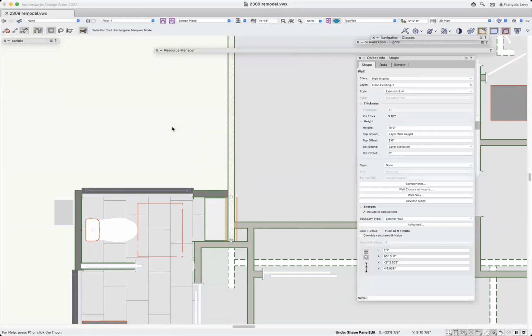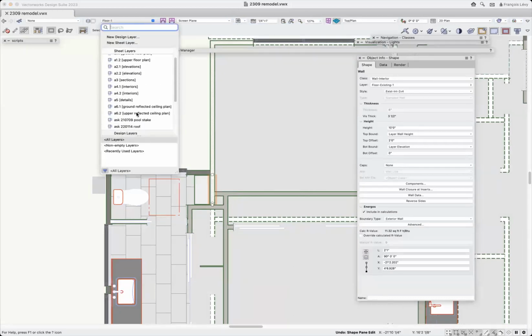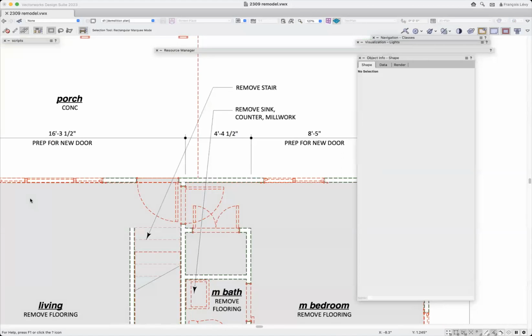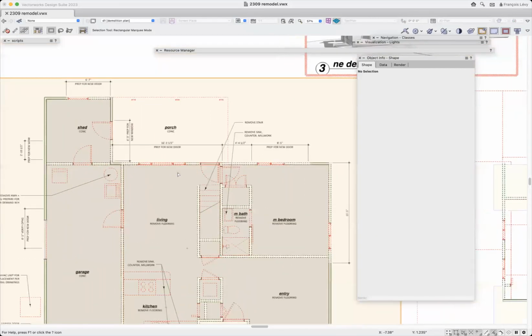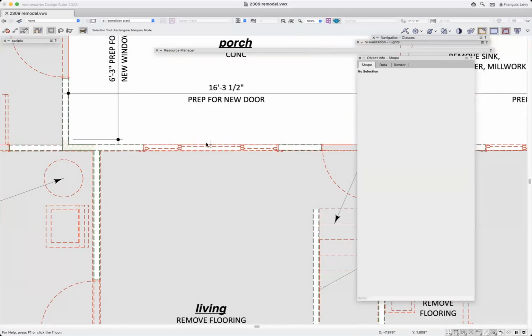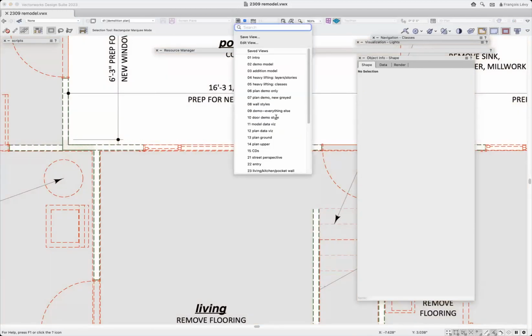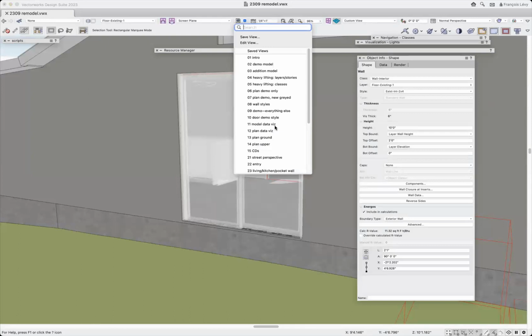I guess the last thing to say about demos in addition is that it's helpful sometimes to visualize those. So if I go to my demolition plan here, right? So here we're sort of zoomed in on this viewport. You can see it's pretty obvious what's going on. Windows and doors and whatnot are being shown dashed with a lighter line weight. Walls are shown heavier, but also dashed that are being demolished. But you may want to do something like what Bill's describing, for example.